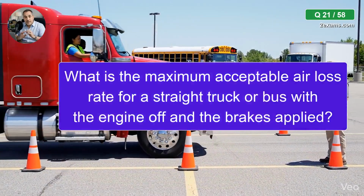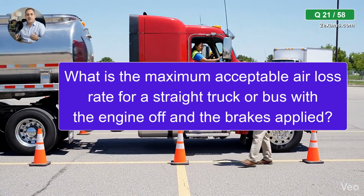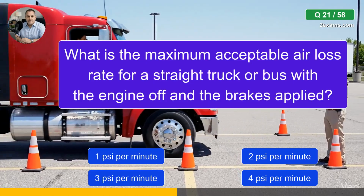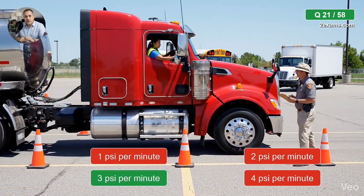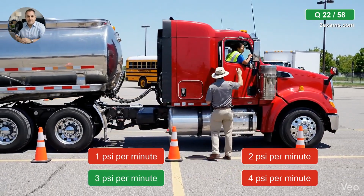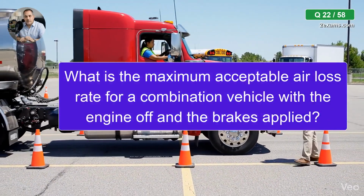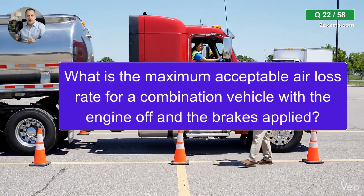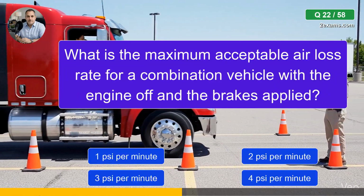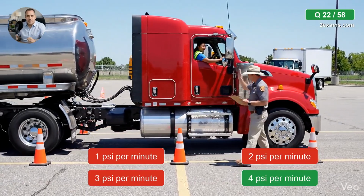What is the maximum acceptable air loss rate for a straight truck or bus with the engine off and the brakes applied? The correct answer is 3 psi per minute. What is the maximum acceptable air loss rate for a combination vehicle with the engine off and the brakes applied? The correct answer is 4 psi per minute.